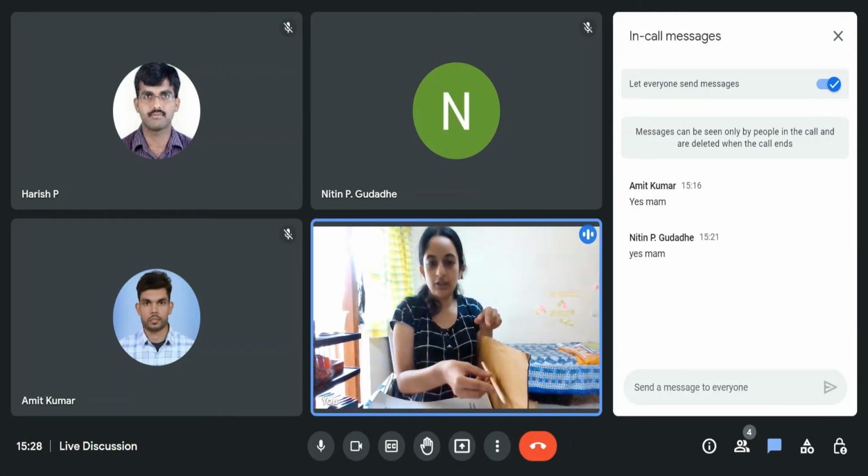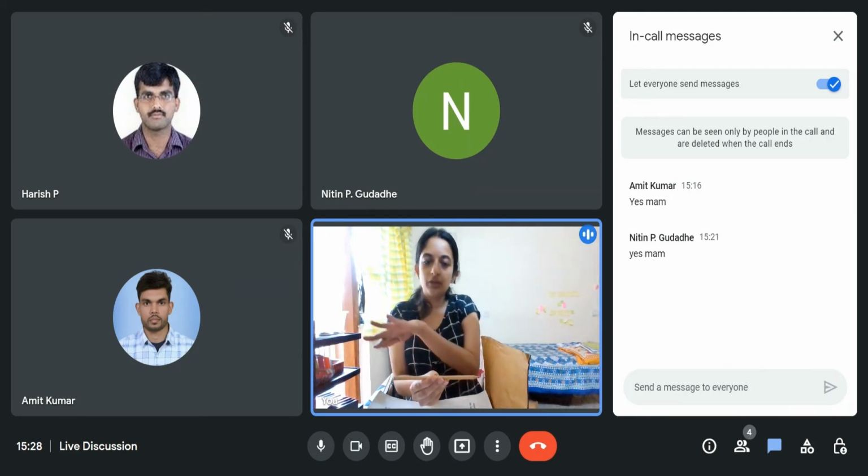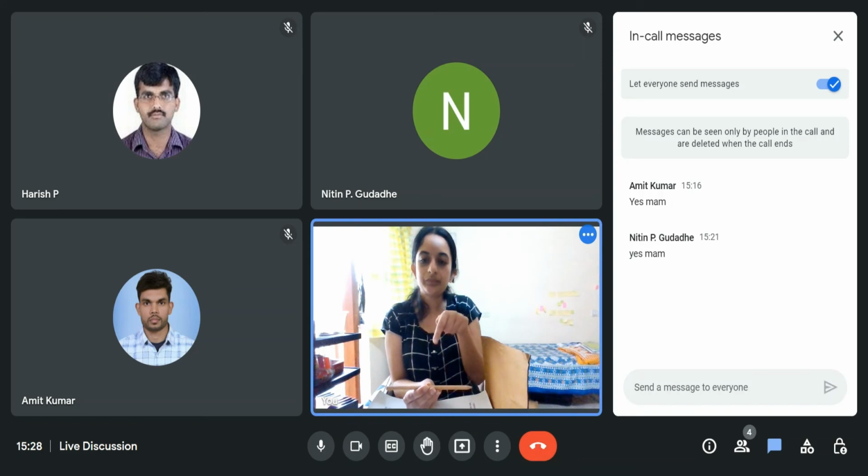So again, the orientation is like this. Apart from being parallel to the horizontal plane, it is now perpendicular to the vertical plane. So this is always parallel in any angle. It is perpendicular when I am looking at it like this. So in the vertical plane, I'll see a dot, and in the top view, I'll be able to see the true length of this pencil.